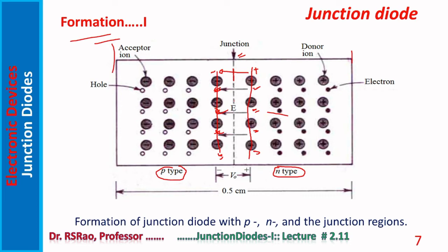only these electrons and holes have a chance for recombination. Other columns of electrons and holes cannot move because their energies are not sufficient to overcome the opposing force that is exerted by the field that exists across the junction region. This explains how junction region comes into being.